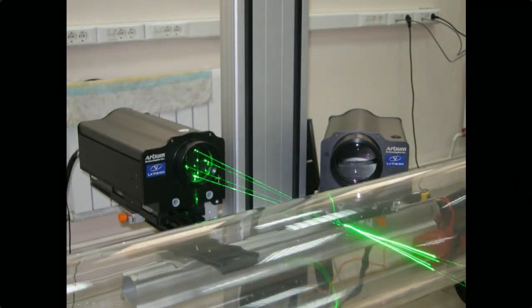We've made systems for industrial applications. In this case, we needed to make measurements in this pipe flow, and these types of configurations are relatively challenging. In this case, we have a perspex pipe with a relatively thin wall, but nonetheless, when you direct a beam through a cylindrical surface, the beams are going to be deformed and the intersection angle changes somewhat, which we had to compensate.